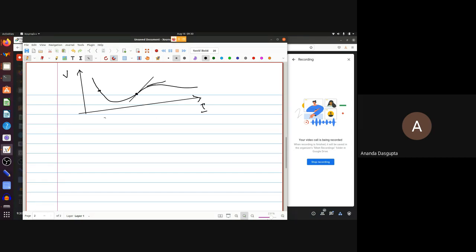Now, if you use a single Z parameter equivalent model for all quiescent points to describe this, so suppose your quiescent point is here, then your model will give you a very good explanation of what happens close to this point. So if your I fluctuates slightly, you get a very good explanation. But if your I fluctuates this much, then the Z parameter model here will give you completely wrong results. Remember, in science we do controlled approximations. We do approximations with the full knowledge that we are approximating. So if your approximation fails, you should know where to look. What kind of things could have gone wrong?